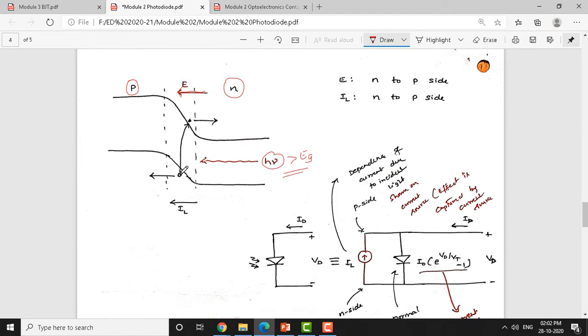This creates an electron hole pair. This is called carrier generation. You can see the electron is here and the corresponding hole is here, and the field here is so strong that it pushes the electrons to the N region and holes to the P region. Okay. So, this is what you are seeing, the arrow marks show electrons moving into the N region. So, here the drift process comes into the picture. Electrons are drifted to the N region and holes are drifted towards the P region.